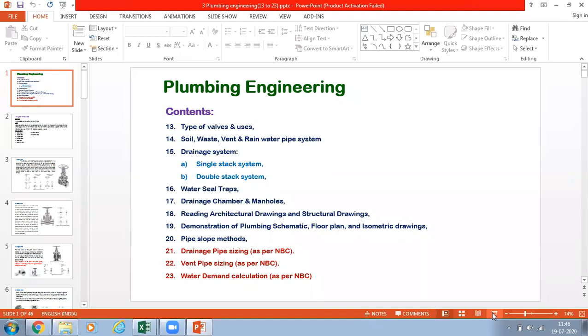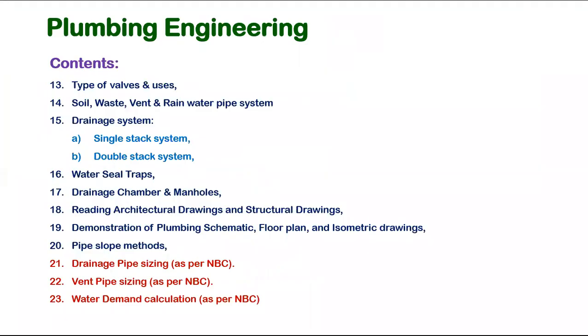50 mm, we are using butterfly valve or gate valve based on the client requirement. Butterfly valve cost will be very low comparatively, and gate valve cost will be more. But from an accuracy, life of valve and maintenance point of view, the gate valve is better. The butterfly valve cost will be less, but accuracy will not be there. Some drop leakage will be there sometimes. So for low cost purposes, we are using the butterfly valve for above 50 mm sizes.